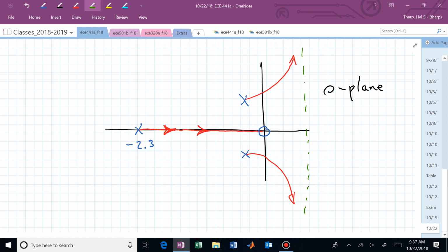So those root locus branches will actually, one will shoot up to infinity at j omega, and the other one will go down as k gets increased from 0 to infinity down to minus infinity in the imaginary direction. That's one possible pattern.